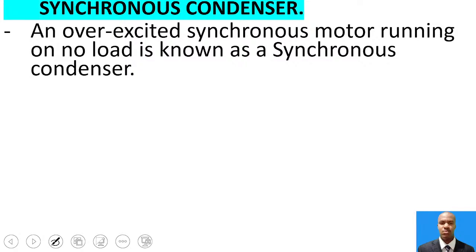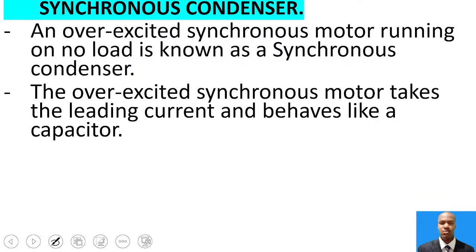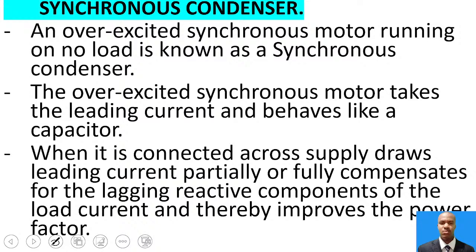The leading current drawn by this synchronous motor partially or fully neutralizes the lagging reactive component of the load current, thereby improving the power factor.